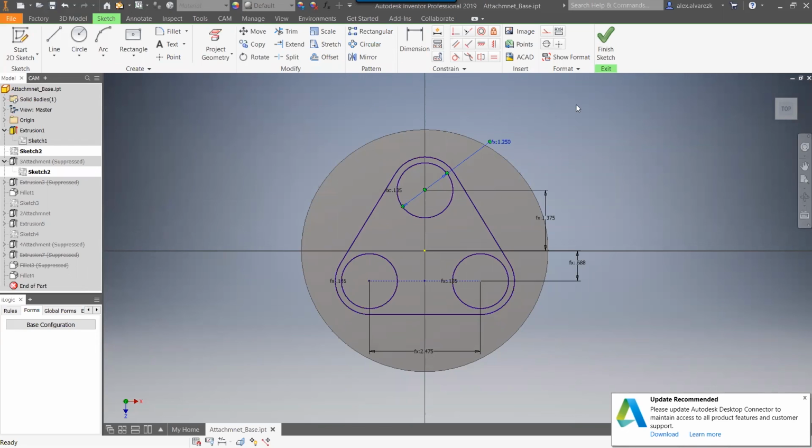It's like, well, it makes it easier if, when you're making these sketches in the first place, you denote those dimensions as whatever the parameter is in text, equals, and then whatever number or equation you want to use. Even if you're not going to be doing design automation, that's just good practice. Maybe down the line you do decide to do some sort of automation with that part. It's already going to be set up for you and ready to go, right? So it takes a little bit longer to do the parameters, but down the line you're just going to be helping yourselves out, at the very end.